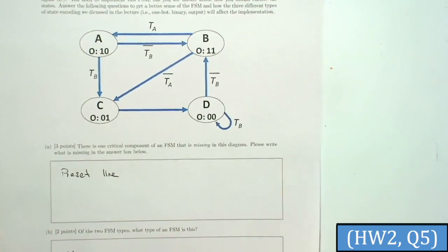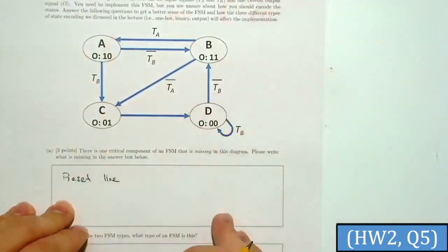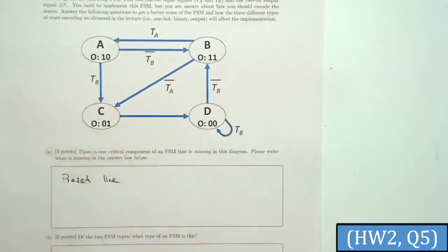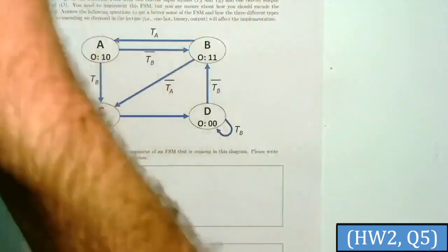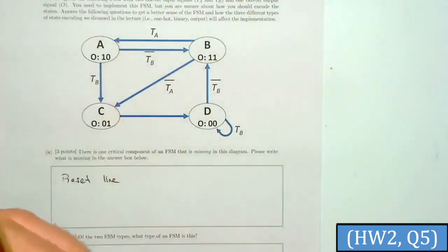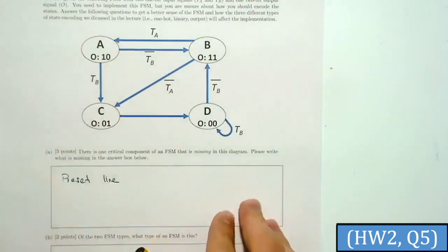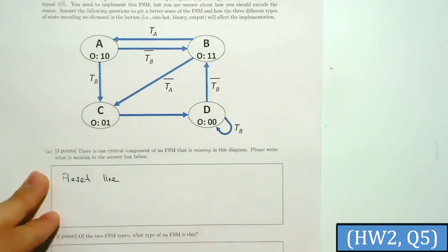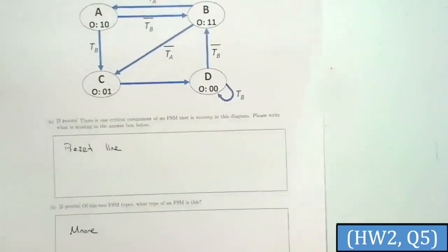For the representation, you can say that this is our initial state, but to really have it as an initial state, you should make sure that when you start this FSM, it's really going to be the initial state. So how do you ensure that? You need some sort of reset line so that it goes there when you reset, and then you start at the initial state. So basically, it means the same thing, to have the initial state and the reset line.